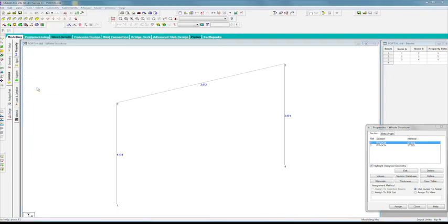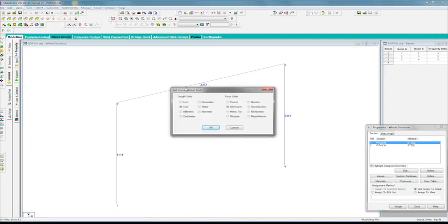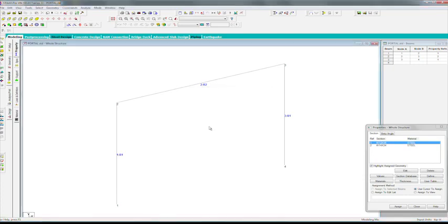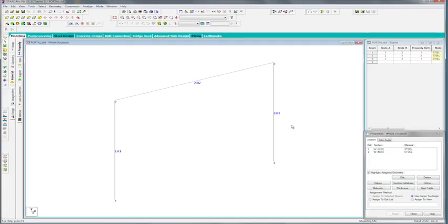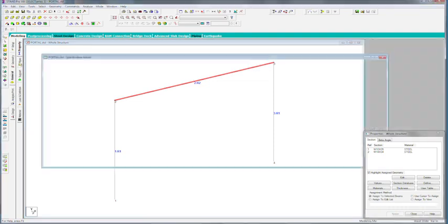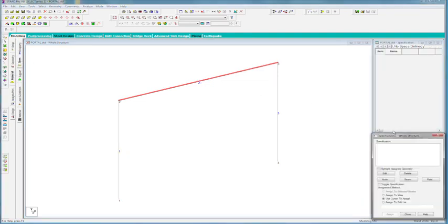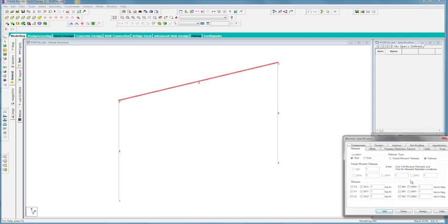Let's do that. We'll click on that, and up comes this dialog box where we can switch quickly over to the inch unit, because we're going to be working with some precision now, and say OK. So every unit we now enter will be in inches. In order to input the offsets, first we'll select the beam, then we'll go over and select General Specs. Up comes this dialog where we can specify things. We'll be specifying information about the beam.